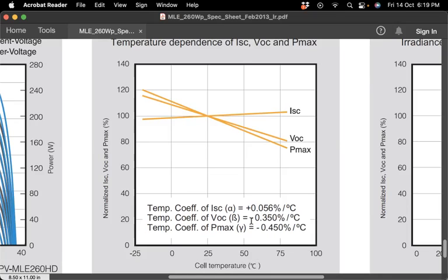So this is a very important effect, and it is extremely important to consider the effect of temperature when you are designing your solar cell in what we can call harsh conditions with respect to temperature, because your solar cell will be degraded, or you'll have a reduction in your power with each degree Celsius increase. Let's make a very simple calculation.